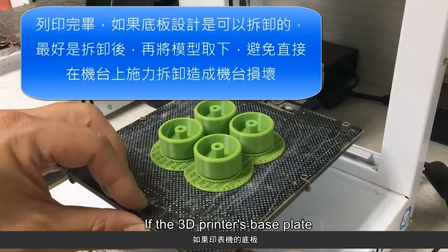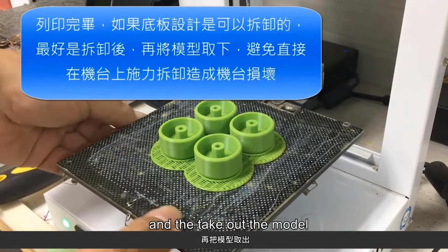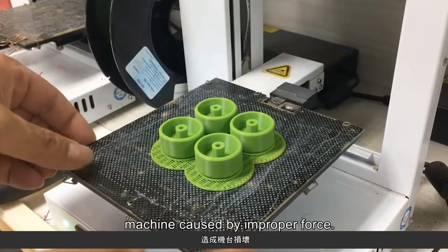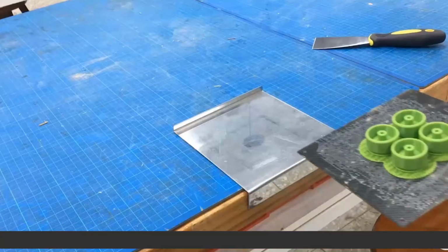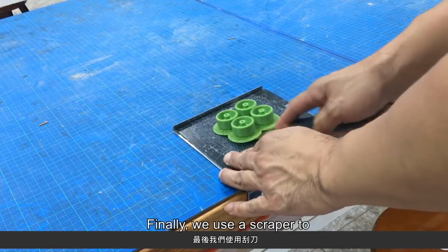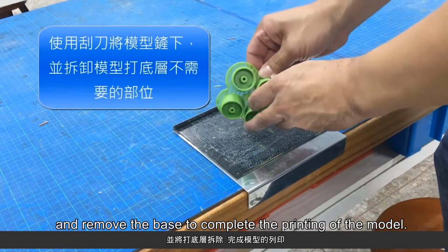If the 3D printer's base plate is designed to be removable, then we opt for removing the base plate first and then take out the model so as to avoid damage to the machine caused by improper force. Finally, we use a scraper to remove the model from the base plate and remove the base to complete the printing of the model.